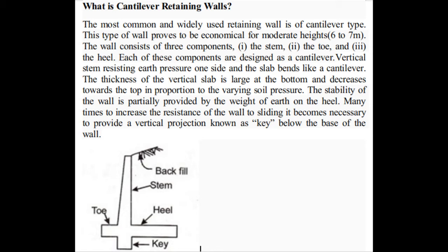The stability of this wall is partially provided by the weight of the earth on the heel. Many times, to increase the resistance of the wall to sliding, it becomes necessary to provide a vertical projection known as key below the base of the wall.